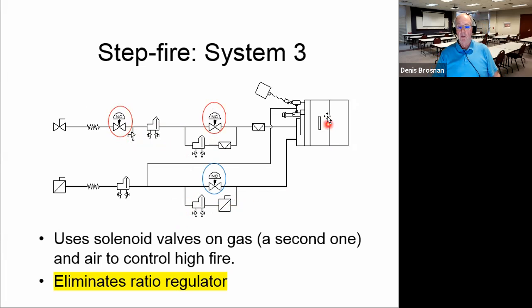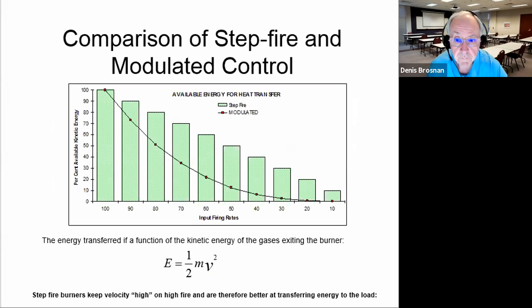Now, most people aren't going to let burners sit in a kiln with no air flow through the burner. The reason is that the air is cooling that burner tile, the refractory part of the burner. If you had no airflow at all through that burner, it's going to get as hot as the kiln is, and perhaps get too hot. So typically we'll maintain some minimum airflow or minimum gas and airflow through a burner system.